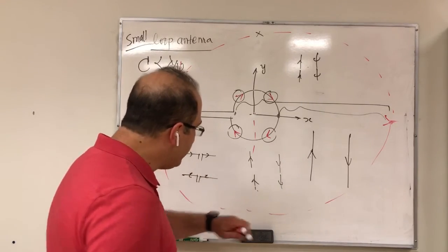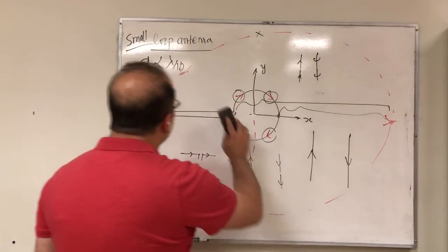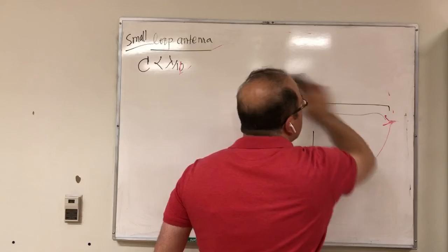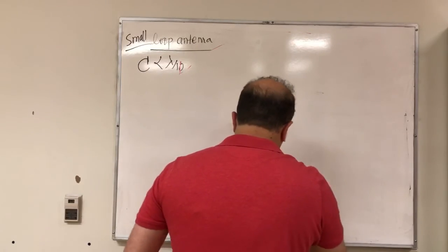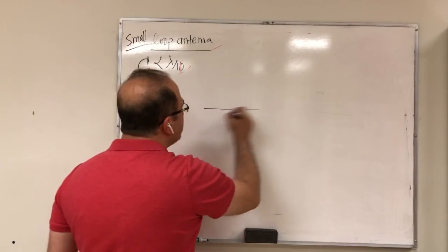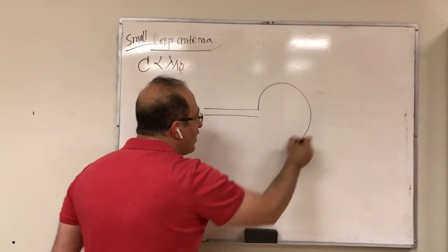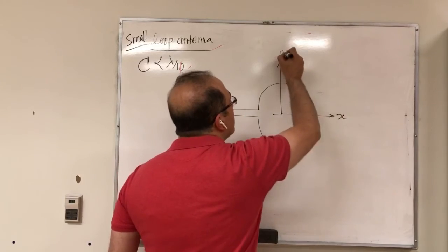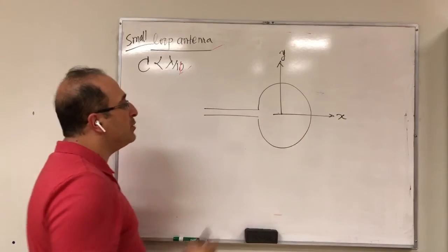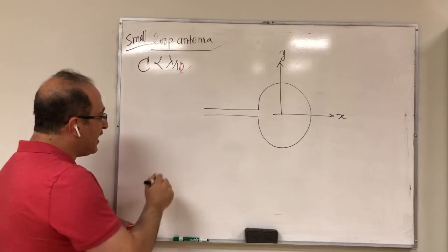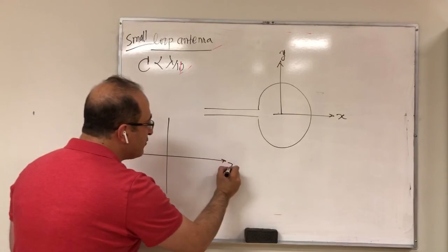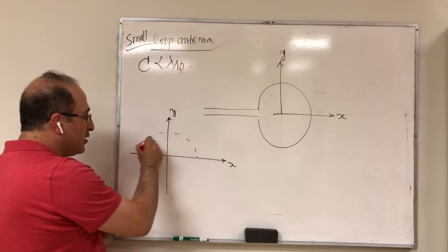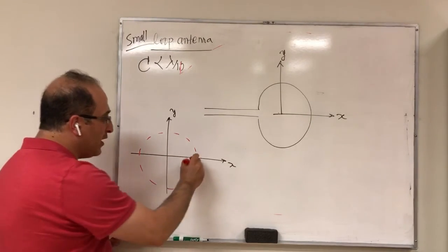So now, if I go by this logic, then I can say that if I have a loop antenna, and I need to correct myself, if I have a small loop antenna, and the z-axis is toward you, the pattern of the antenna in the xy plane is in fact omnidirectional, because if I go around the antenna, I get the same thing.